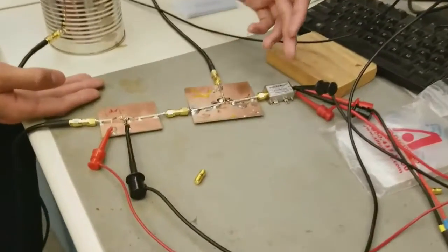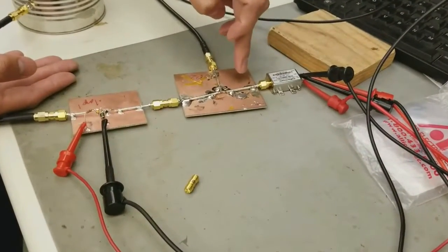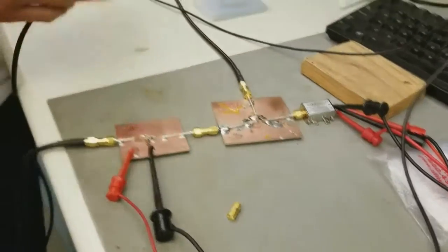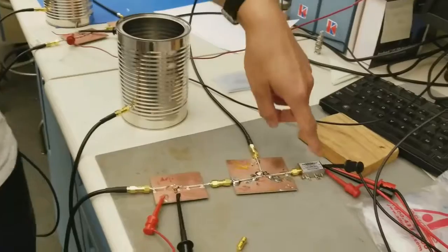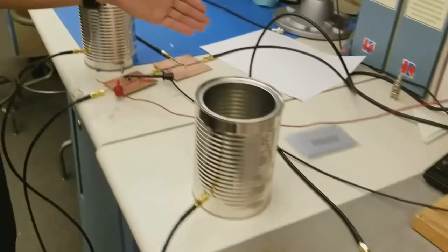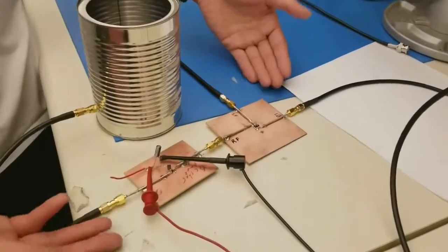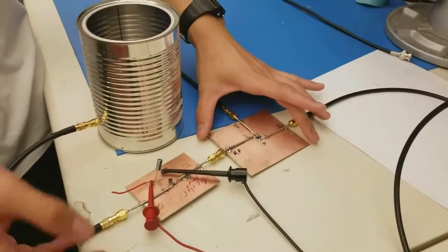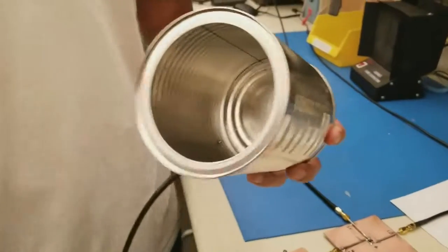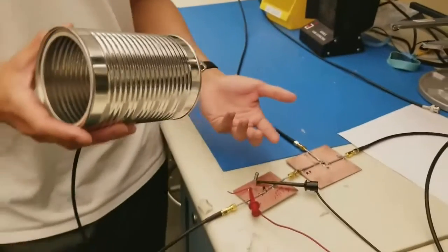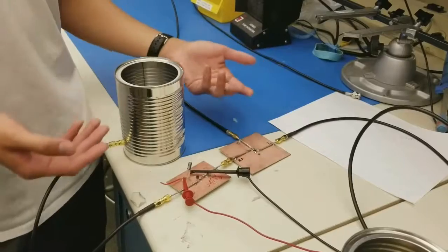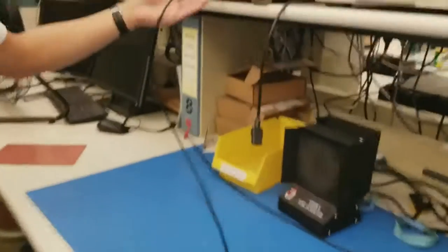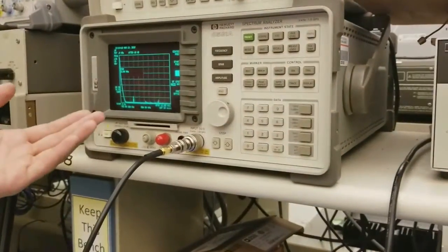And moving on, this is our transmitter side, where it goes from VCO to splitter to amplifier and to our antenna, which transmits. And the splitter will split from transmitting down to the frequency mixer, which is our receiving end. So you have the frequency mixer, the amplifier, and the receiving antenna. Our input will be the receiver, it will go through the amplifier to give it some gain, and it will be mixed from the LO coming from our VCO and whatever our RF is to give us an output to read as our IF on the spectrum analyzer.